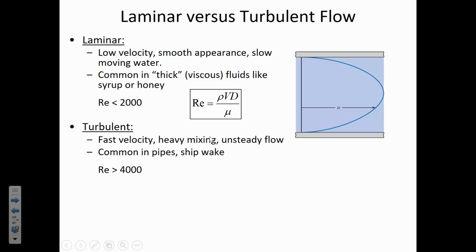During the experiment we'll do in the lab to visualize laminar versus turbulent flow, what we're going to do is we're going to try and, with our eyes, see if we can identify the point at which the fluid becomes turbulent and starts to mix. So we'll see if these Reynolds numbers that are typically held, 4,000, that's a rule of thumb. But anytime you see a nice round number like this, you should be skeptical. Like, who decided it was 4,000?